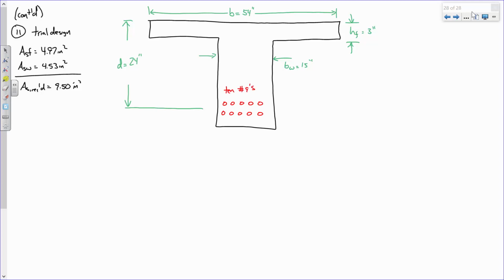So when I look up my beam width requirement, I don't look up the width requirement for 10 bars, I look it up for 5, right? And if you go to your beam design aid, note that the d distance goes to the center of that steel. Note, for 5 number 9s, the beam minimum is 14.28 inches.